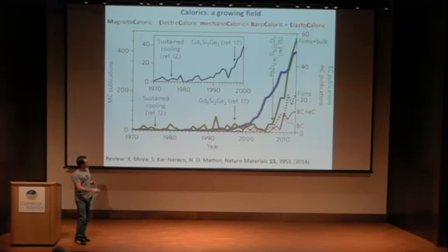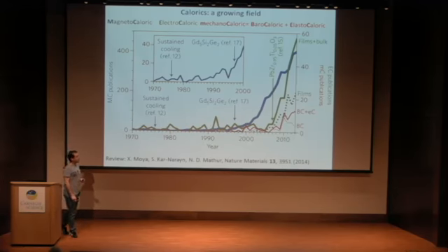You see that, especially for ferroelectrics, one of the first works was done in the Cambridge group with Neil and Jim Scott at that time, where they showed that in PZT thin films, you may have a rather strong adiabatic temperature change just by applying an electric field. This is the green curve here.